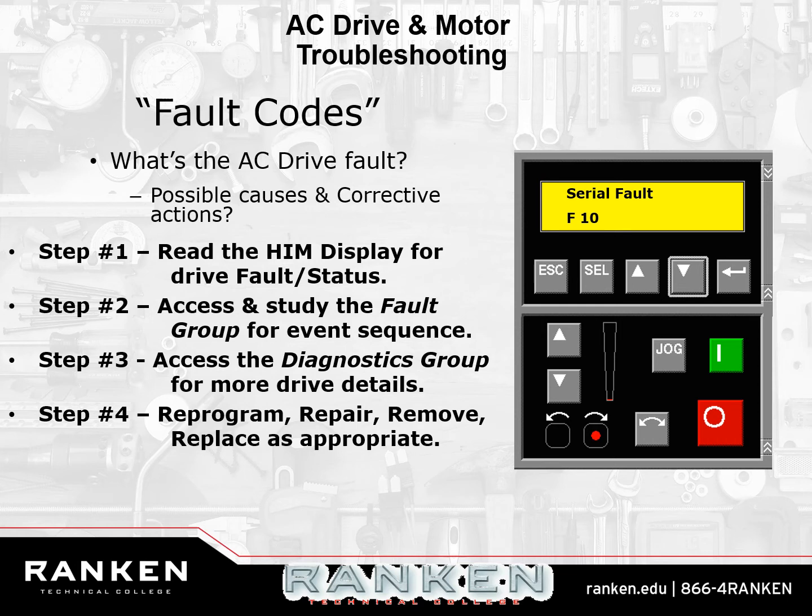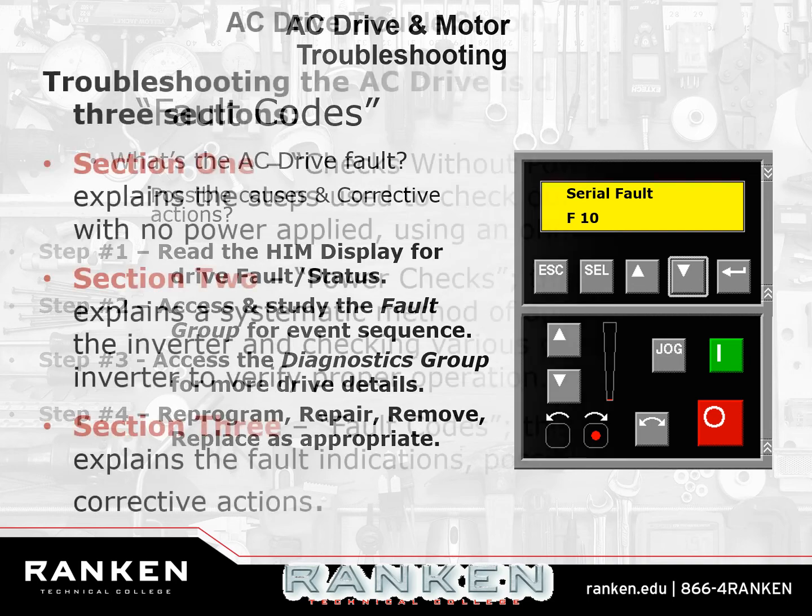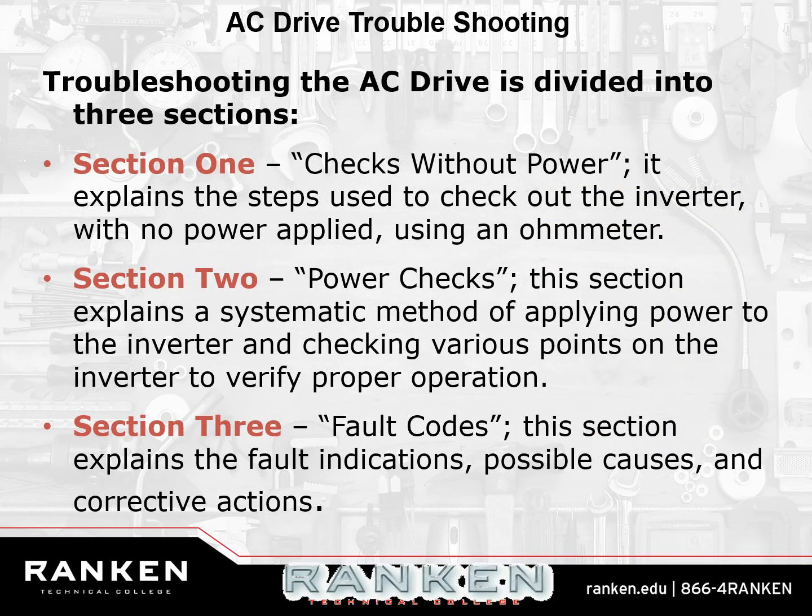And then if you have good voltage at the top of the drive, then check the bottom of the drive, and then put it in manual mode and turn it on and see if it goes. Or it'll tell you to up the current setting or something like that to see if you can get it to run. A lot of times the fault codes are really ambiguous though.